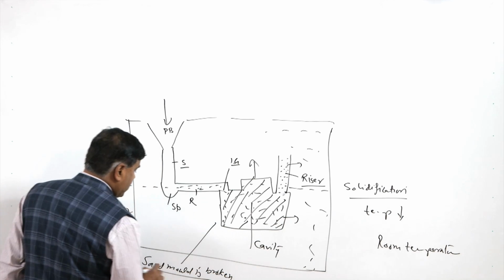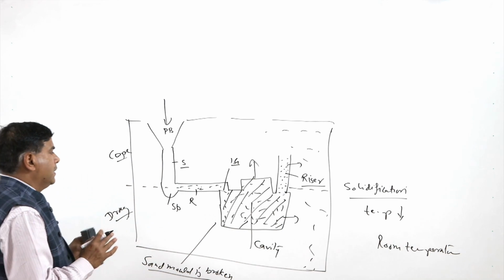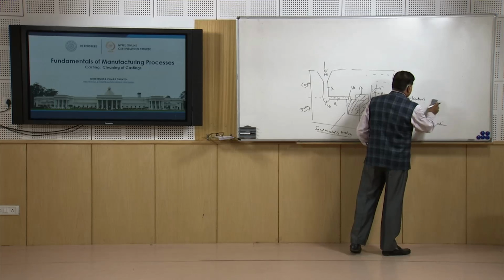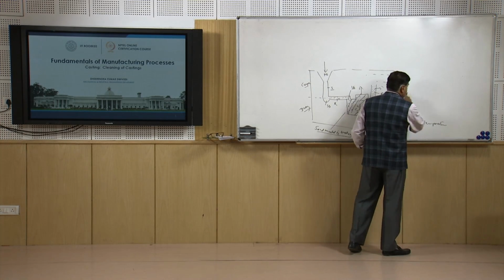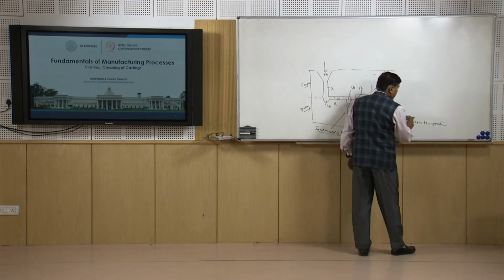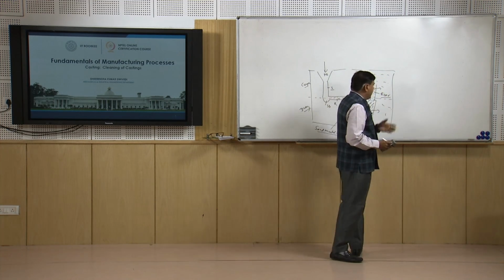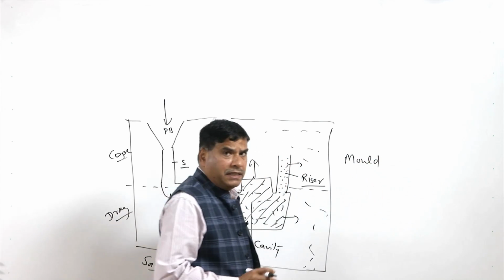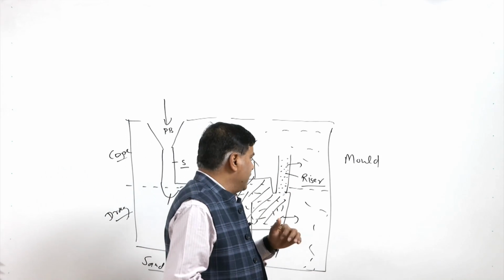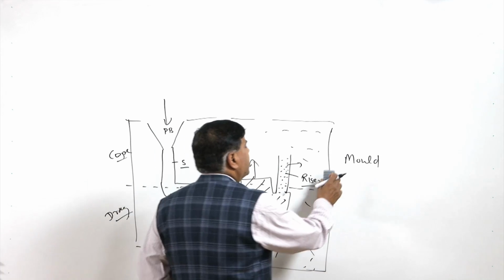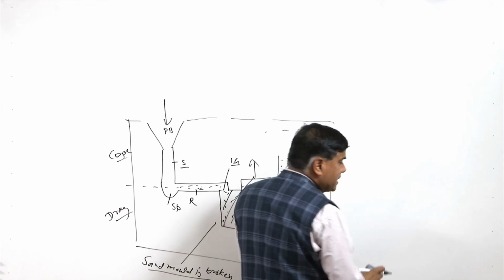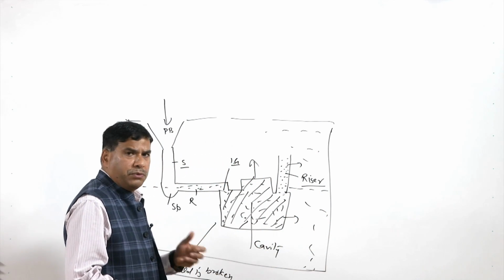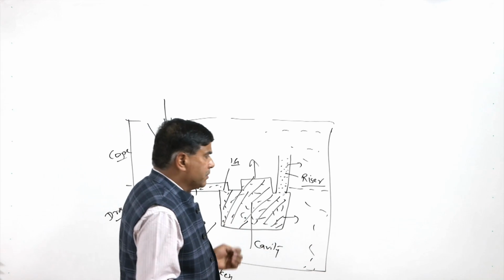At which stage, means at which temperature, the sand mold should be broken so that the casting remains intact and as per the requirement, with the desired characteristics and quality? Because if the mold is broken at a high temperature, then it can lead to the breaking of some of the parts which are thin in section, and it can lead to warping, or due to the residual stresses, it can lead to cracking.